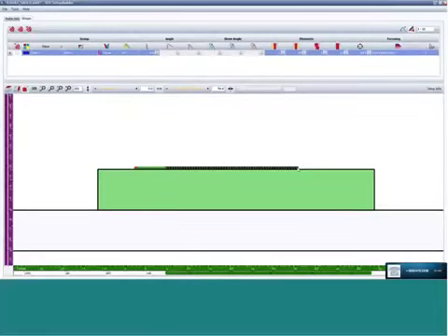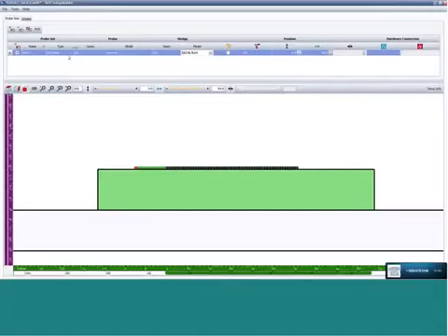As you can see, the A2 probe is asymmetrical in the housing, meaning that there's empty space in the housing on this side. So it becomes relative which side of the probe you're using for the inspection. Some of the same models of A2 probes, such as the 2 megahertz version, are symmetrical in the housing family.